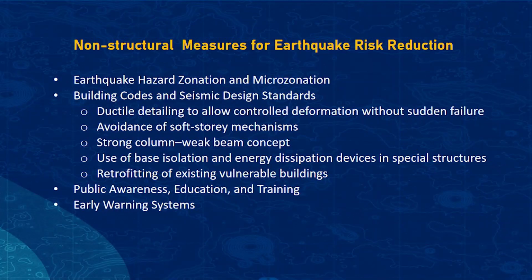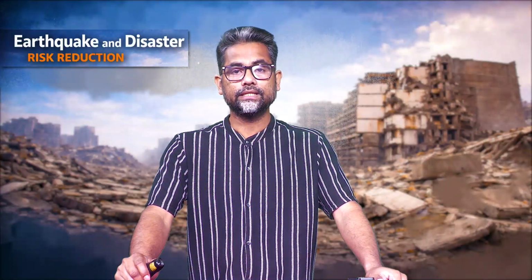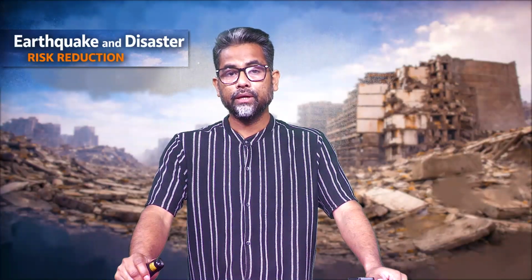Core design principles include ductile detailing to allow controlled deformations without sudden failure, avoidance of soft story mechanism, strong column, weak beam concept, use of base isolation and energy dissipation devices in special structures, and retrofitting of existing vulnerable buildings. Next, public awareness, education and training. Widespread information, education and communication campaigns, integration of earthquake safety into school curricula, and regular mock drills and community training programs build preparedness.